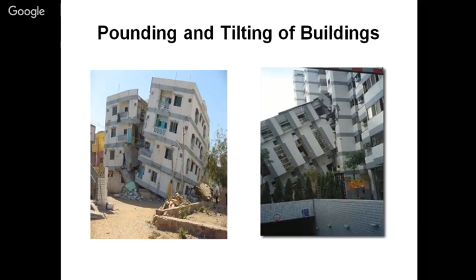If you are not maintaining those gaps, then in case of an earthquake, pounding is going to occur between these two buildings, and the damage could be worse if the slab levels are not the same in the two buildings. The interstory drift at the slab level is different, it is more as compared to the in-between level of the story, so it is going to hit the wall of the other building, and it is going to produce more damage as compared to the other case.